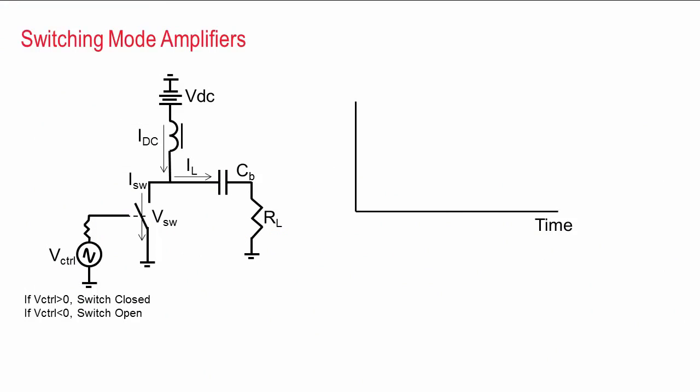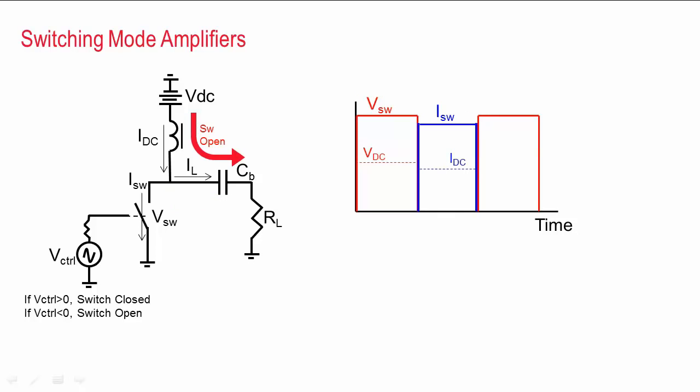First, I think it's important to understand the concept of a switching mode power amplifier. As opposed to the conventional classes of operations, switching mode amplifiers use a transistor like an on-off switch. So when the switch is closed, AC current flows into the switch, and when the switch is open, current flows into the load, which causes a voltage. Now ideally this results in extremely square voltage and current waveforms with almost no overlap, so very little power is dissipated in the switch's heat.